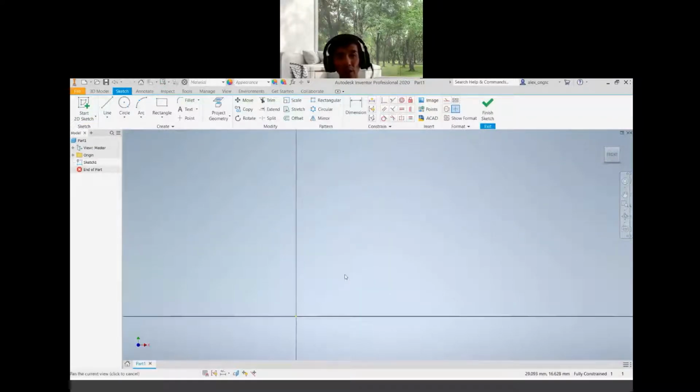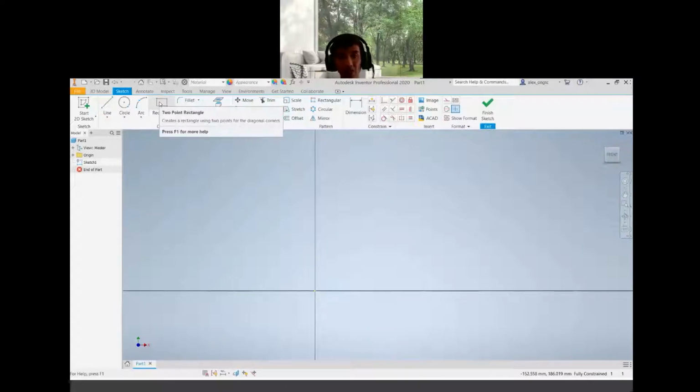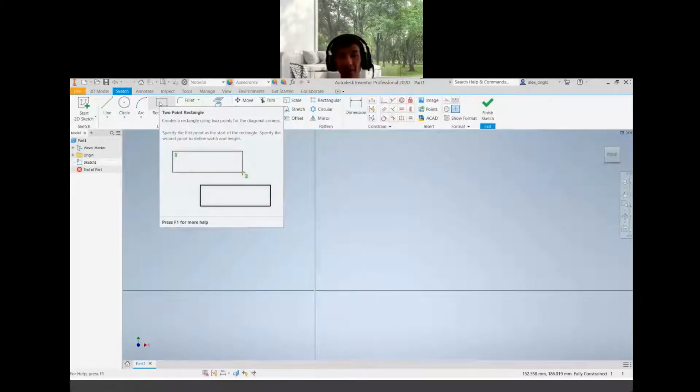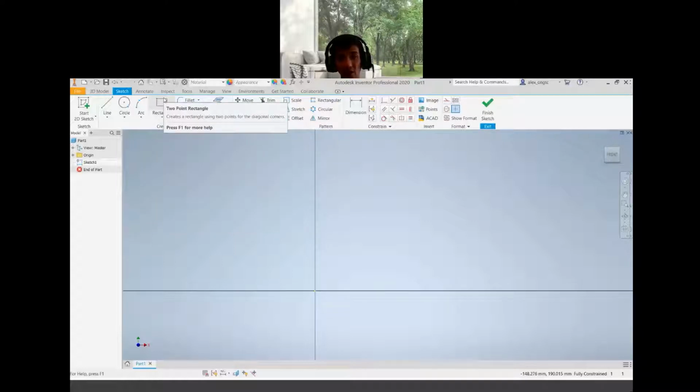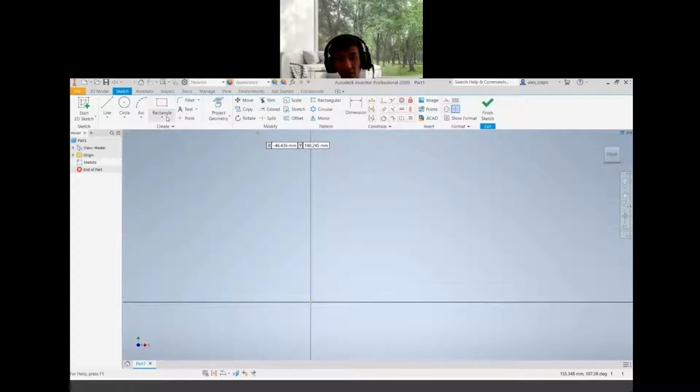What I would like to do is utilize a simple shape, which is the rectangle. I will show it to you, please have a look. It is a 2-point rectangle. I create my sketch like this: first point here, then a subsequent one here. You will see you have one line guiding you. If you click now, you will apply the collinear constraint. You can apply this one here, up to here.